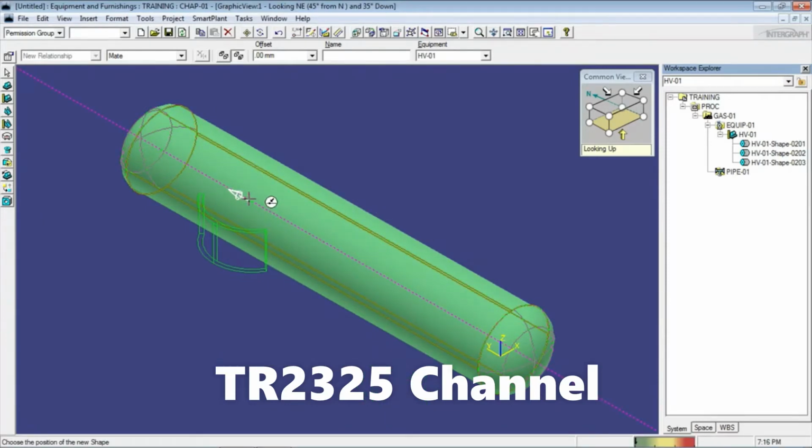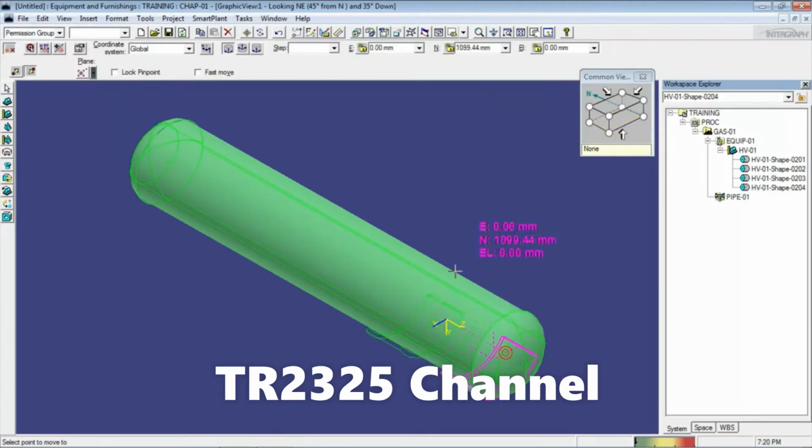Then go to select the axis, unlock the axis, and rotate the saddle using the arrow keys. After that, give the distance from the 0 point. Just for example, I am going to give 1000 from the reference point.